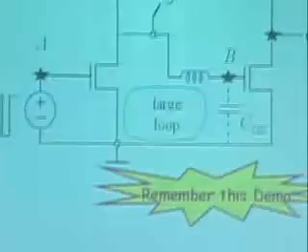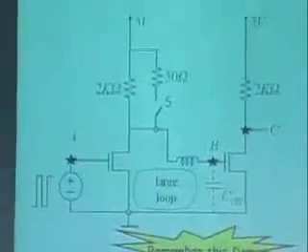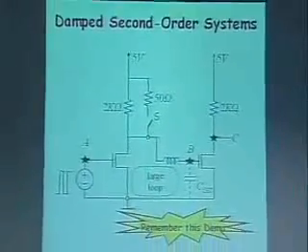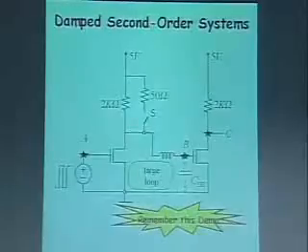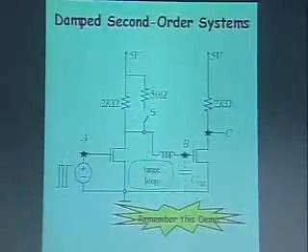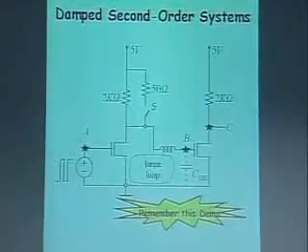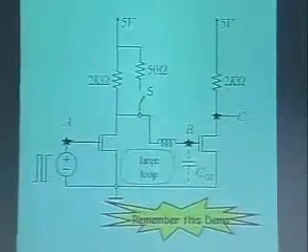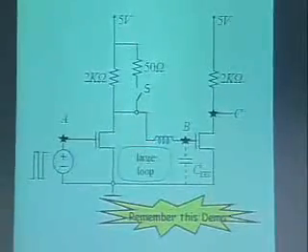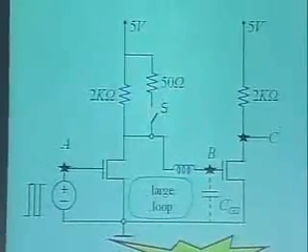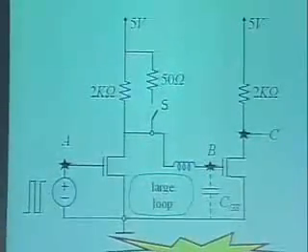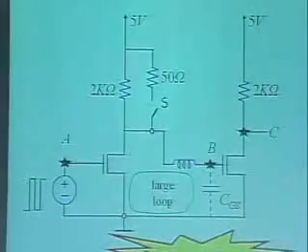Okay. So I began by showing you this little demo. 2 inverters, one driving, I can model the inductance here with a little inductor, the capacitor of the gate here. And recall that when I wanted to speed this up by introducing a 50 ohm, a smaller resistance, I got some really strange behavior.